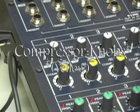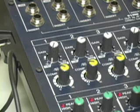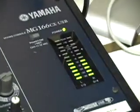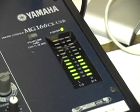As with any input channel, make sure you adjust the gain before you adjust the compressor. Make sure that during your broadcast, neither the level meter on the board or on-air display go into orange.